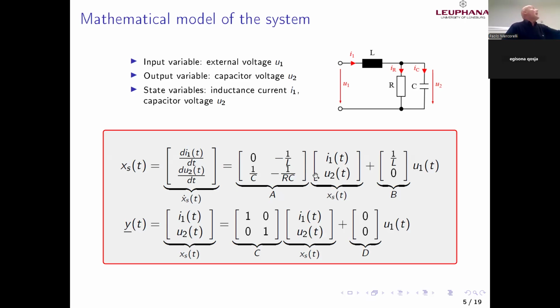Of course, it's another system, we can recognize also from the structure of the matrices. But in any case, do you remember in the motor, we had the two states, current and velocity. Here we have two states, current I1 and U2, the voltage on the capacitor. Because if you remember, the concept of the state represents or reflects the energy. Which kind of energy do we have here?